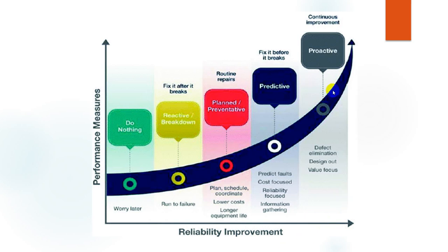But in fact, we found that we have two failures. One is function failure, the other is called performance failure. What does that mean? Function failure is when we have, like, a motor burn, the pump is not working anymore. That's it. Performance failure, like if you have a partially plugged strainer, it could run, but it will not perform. In this case, it will affect reliability.